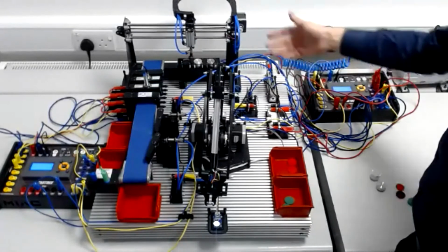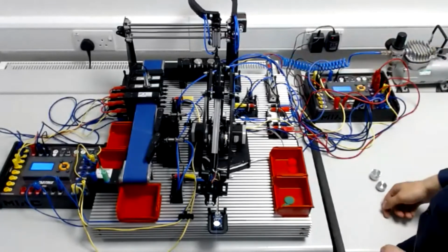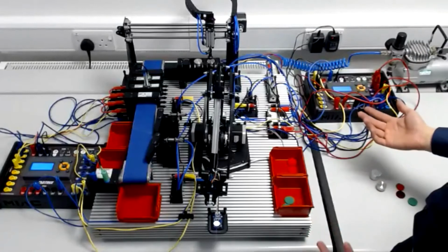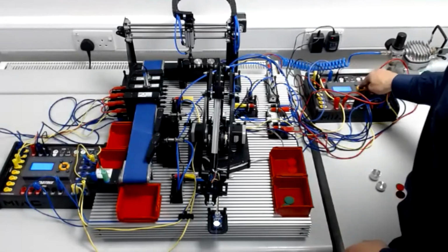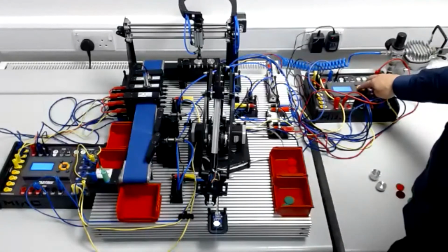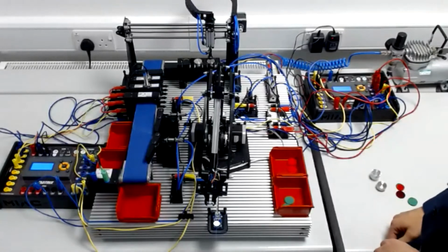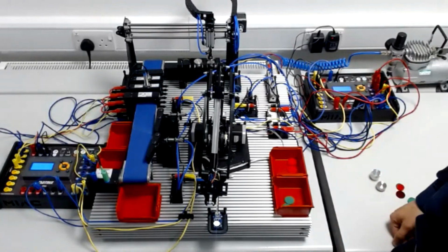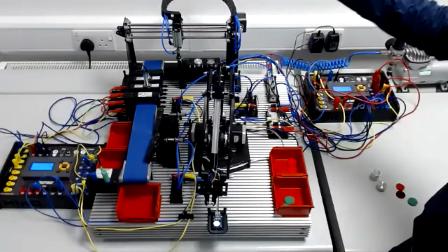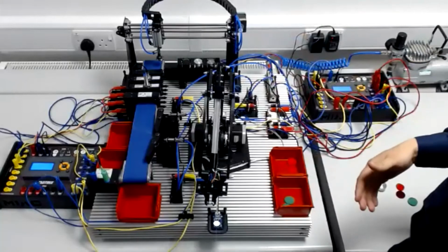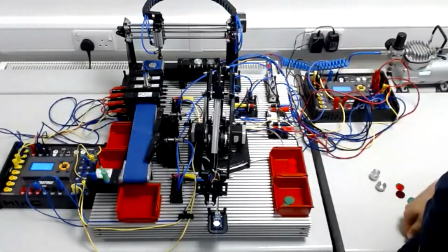So we'll start that. It's going to go home to start with. Then it will start its first motion, and this one's going to hop array for now. So if I turned on the compressor, that would actually start. So I'll start again. It'll go home, and it'll go down this time because the compressor is actually on. So it'll pick up the counter. It's relatively forgivable. The bellow on there gives it a nice sort of undulation left and right that it can move. It will go over, and you can see it's just dropped it on the conveyor belt to the side over there.